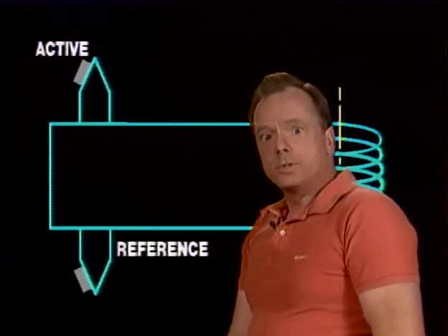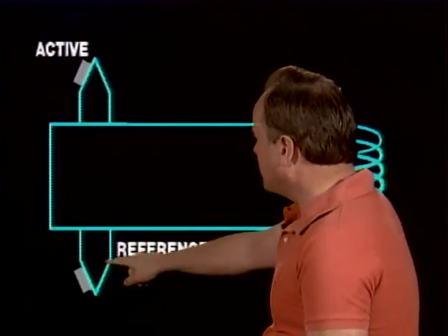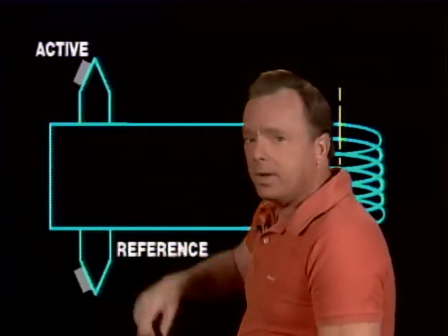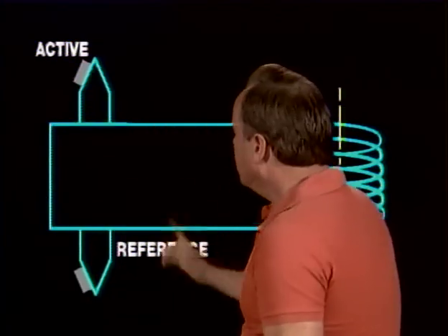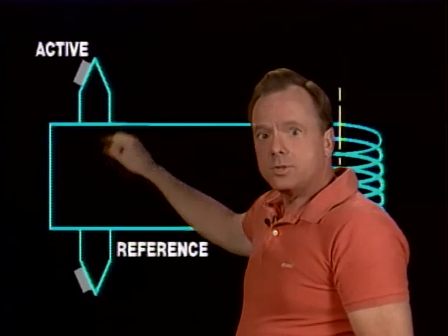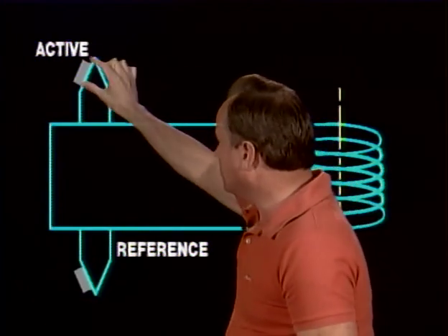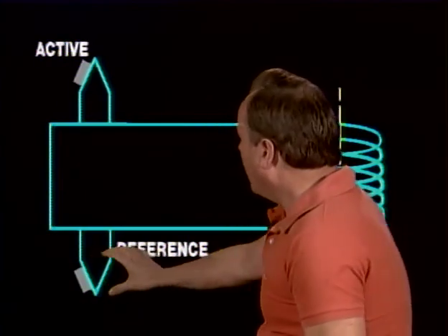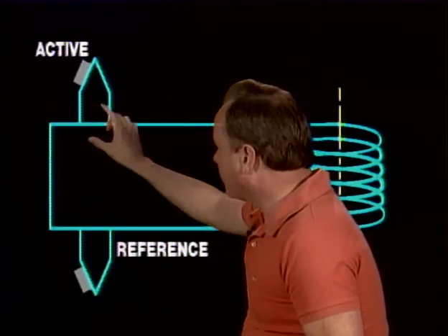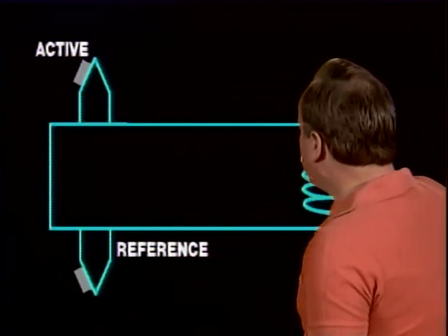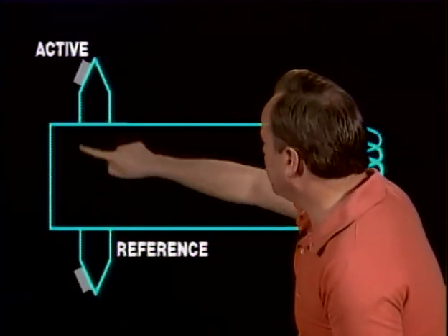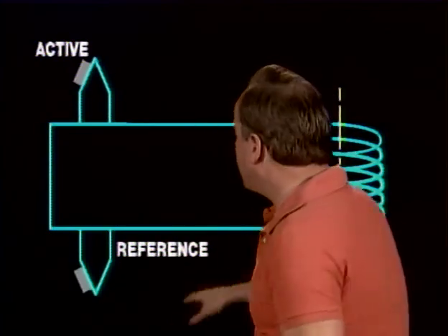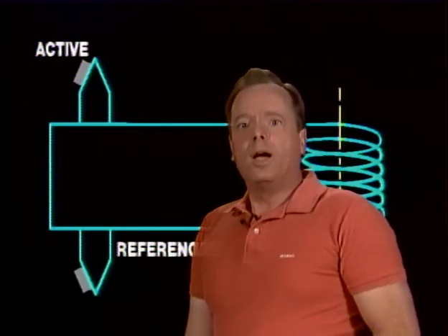Now, the way a thermocouple system works is you have two junctions of dissimilar metals. You'll have a hot junction and a cold junction. The hot junction will be located on whatever you want to measure. The cylinder head temperature will be located right on the cylinder, the exhaust gas temperature located somewhere in the exhaust system. And then the reference indicator will be located generally near the gauge somewhere, the reference junction, I should say. Then the gauge measures the current generated by the difference in the temperature of these two junctions, and the gauge that measures that current is called a galvanometer.